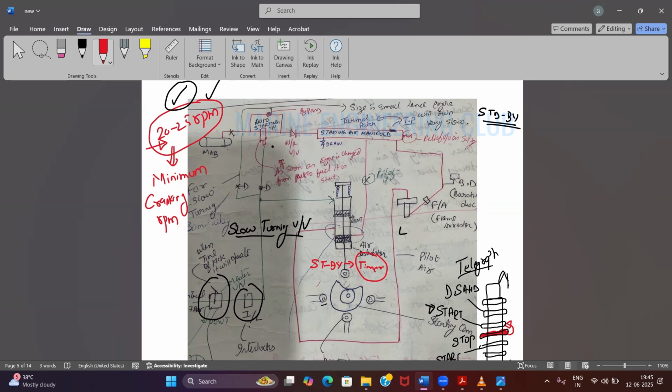Turning is done to take off any matter from the piston crown, the top of the piston. But what is the main purpose of it? It is to understand if my piston is stuck somewhere, to check my piston freeness. Suppose local welding has happened, or micro seizure has happened between the piston ring and my liner.